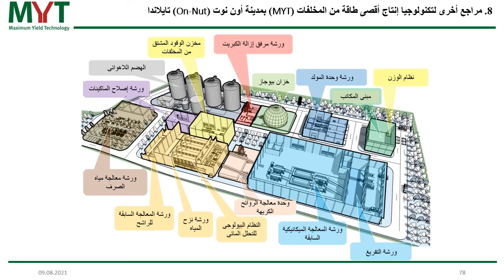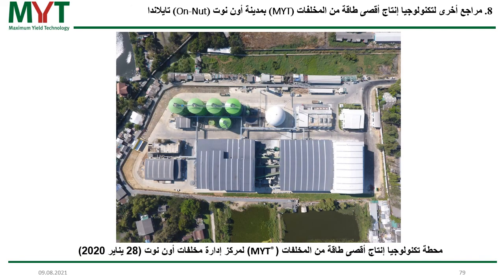Even with 30% of biogenic waste in Germany, we do not need additional water for our process. So the water inside the waste is extremely sufficient, and we take this process water also in a cycle. This I need to tell you. So we have the fresh water, which is coming with the new waste. We have the process water. We have this process water used in a cycle. So after cleaning, it is again applied to the fresh waste, used again, cleaned again. So it's a cycle, and we get always more water inside with the fresh waste. So you do not have to worry that you need too much fresh water for running an MYT facility.